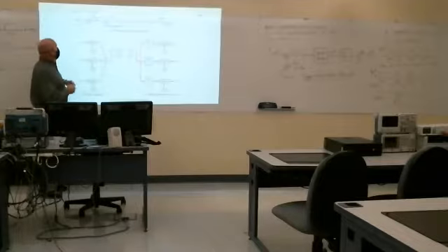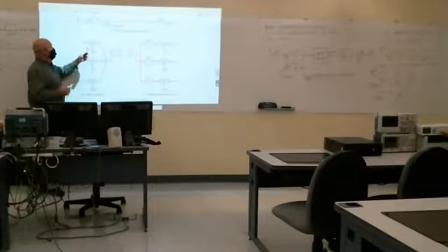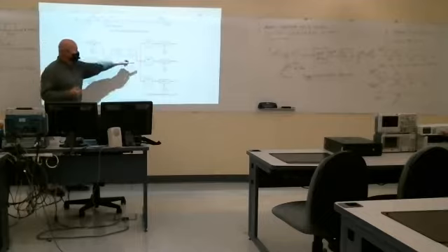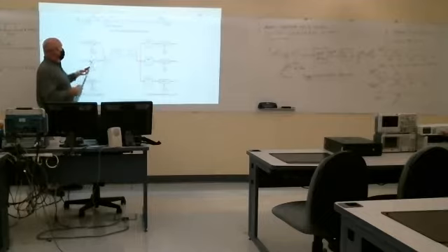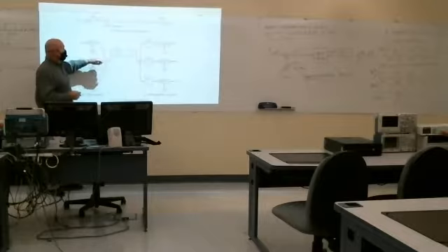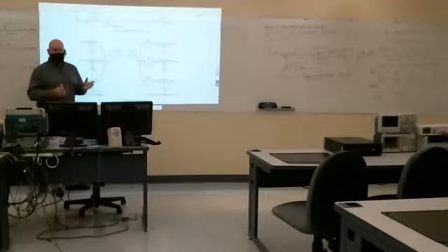I mentioned that they show here that this is a 3.5 kilohertz width. That would be typical for voice, not music. And then there's typically a little space between them so that you can filter them out. But each of the different voice signals is translated up to a different center frequency, a different carrier frequency. And we can sum them together and then transmit them, via antenna, put them on coax cable.